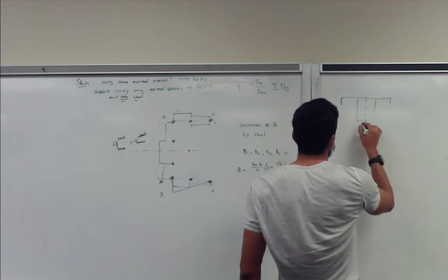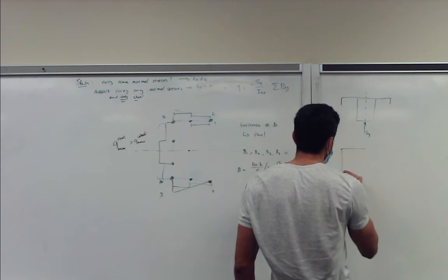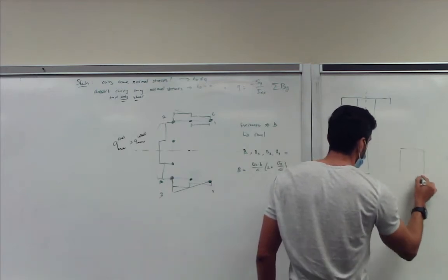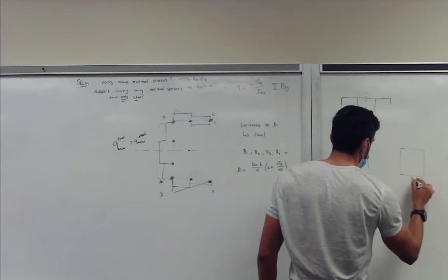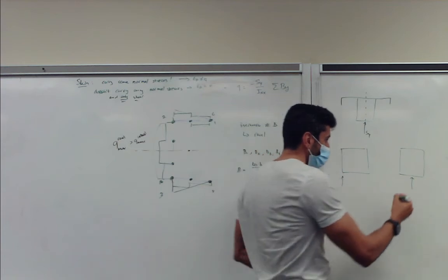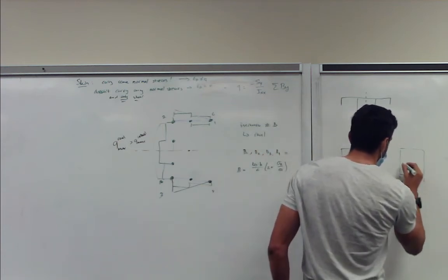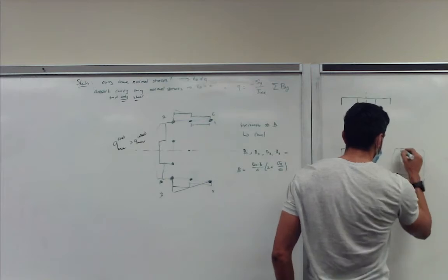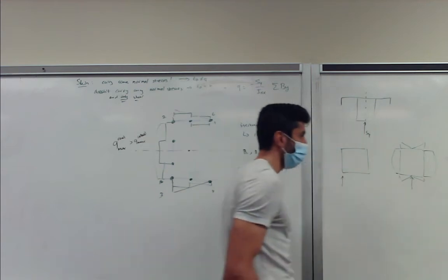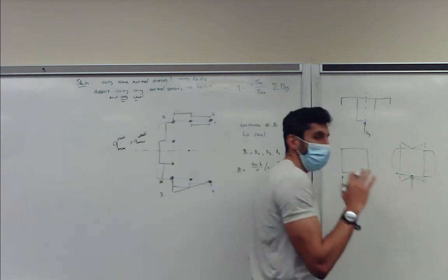Because if you shift left or right, say this one is, let's do a box, it's easier to draw. If you have this, here we can make the cut at this location. Now shear flows will go something like this, based on symmetry, right? So if I now take the moments around this point, then I have symmetric shear flows.